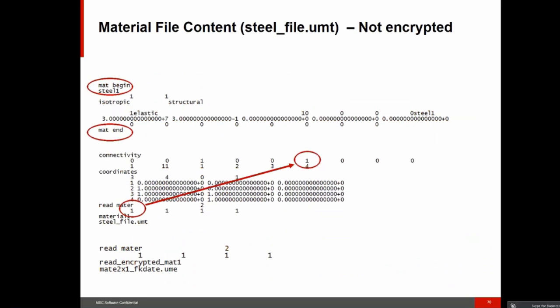And if you have material data, you can build up your own material data by saying material begin and material end. Give the information, include the table IDs, or in this case, the connectivity said this is material ID 1.